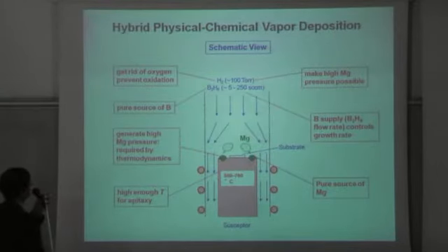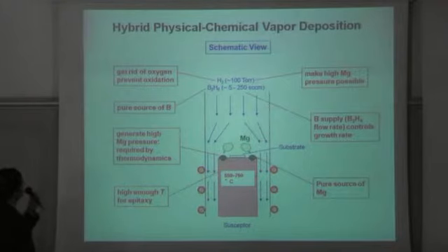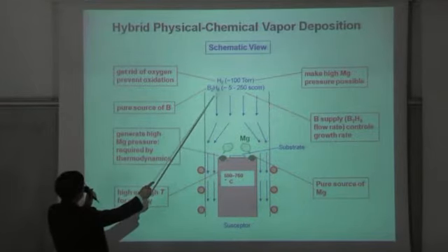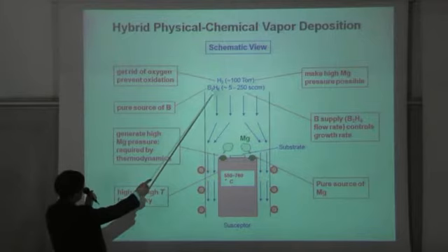In my lab, we use this technique. We call it hybrid physical-chemical vapor deposition. It's basically a CVD process. We use diborane as the source of boron.